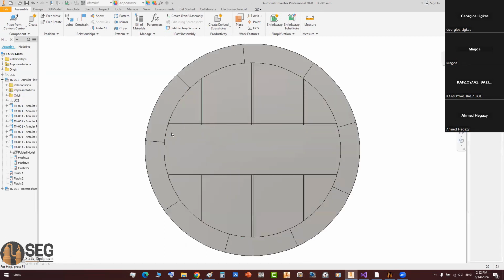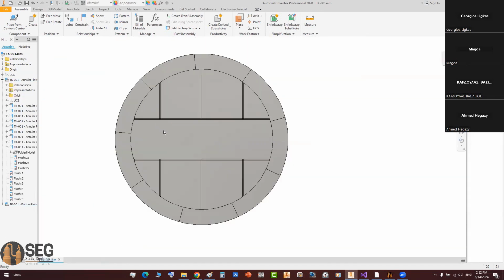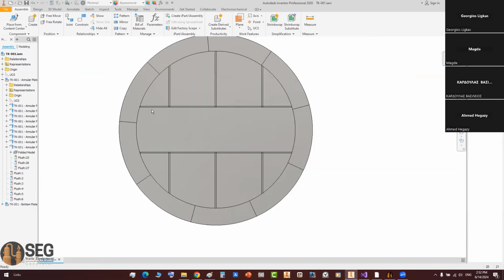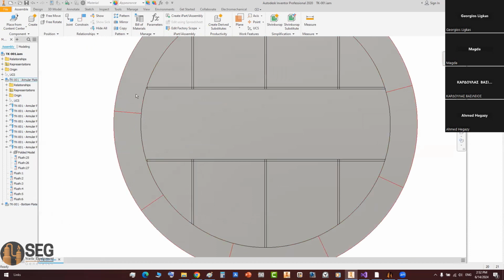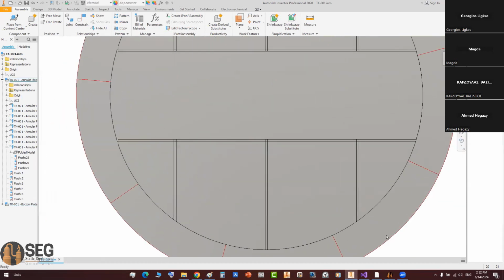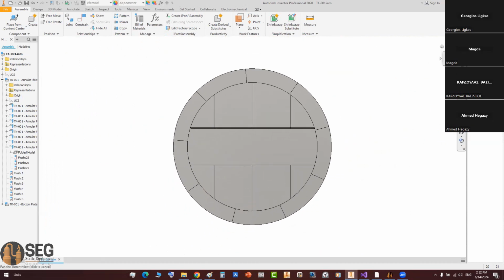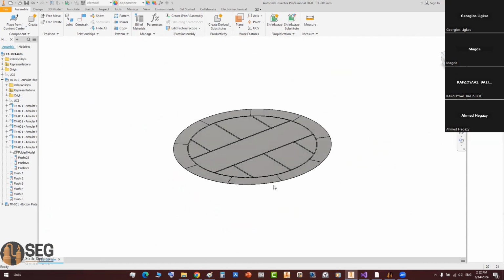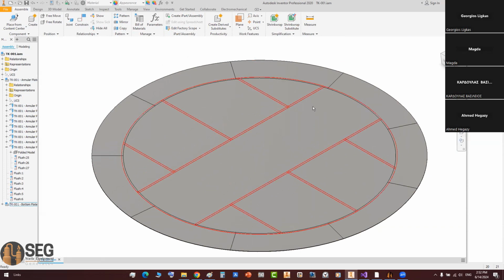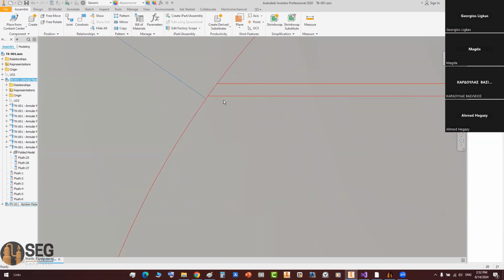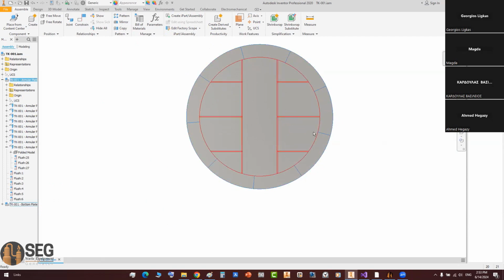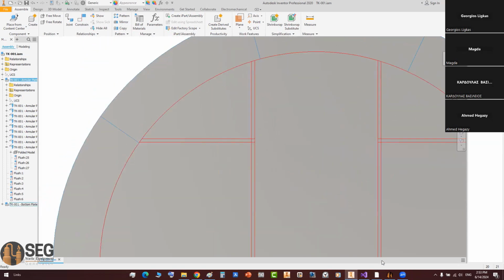Okay, I think we still have the same issue in this plate. Okay, no problem. Let's complete that, and after that I will check why this plate did not become complete. Okay, now we have the annular plates with the bottom plates like that. Let's add the first can for that tank. But as you can see here, if you take a look, you may have some welding lines near each other. We may need to change the orientation a little bit.